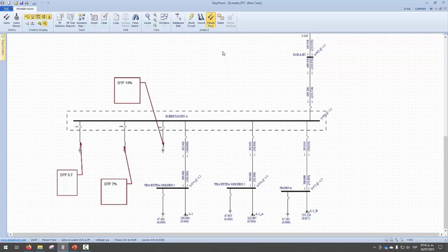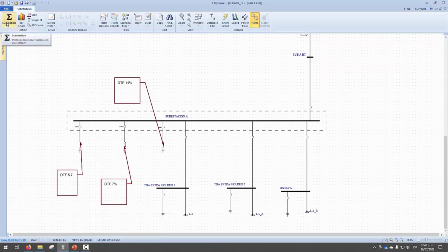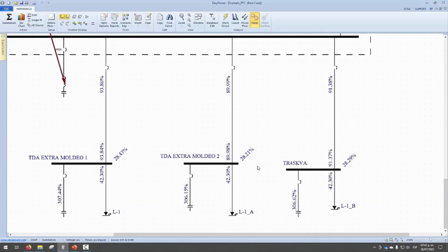But then I go and check what happens on the harmonic side of my facility, right? So I make a new measurement, and I find that I have an unusually high voltage distortion, total harmonic distortion for the voltage, and for the current. And these capacitors, instead of lasting 10 years, are just lasting 6 months because they are absorbing too much harmonic current. So, how was I before the solution?